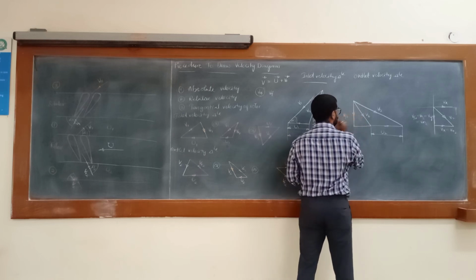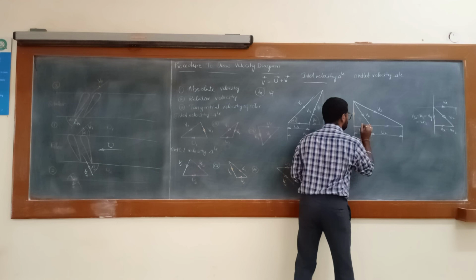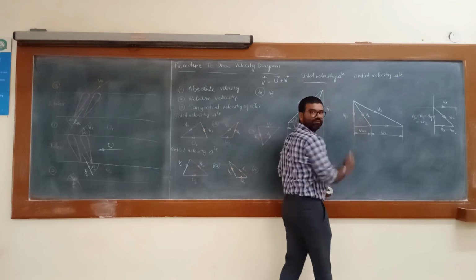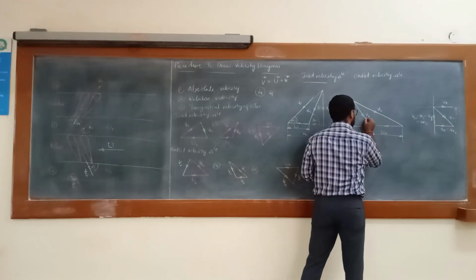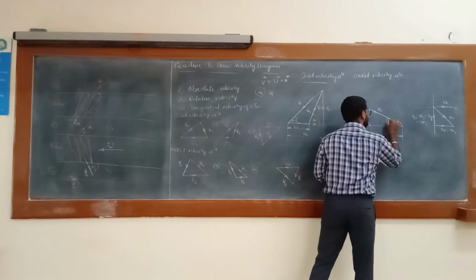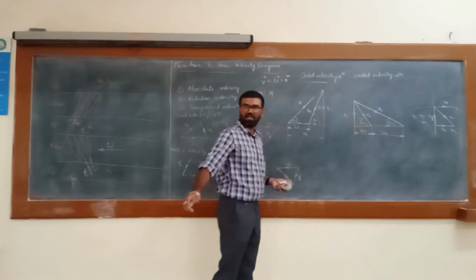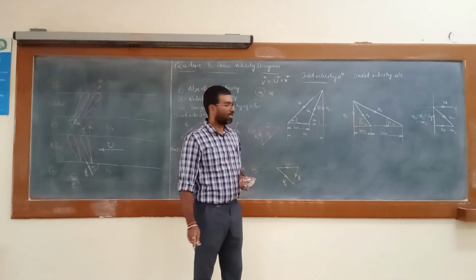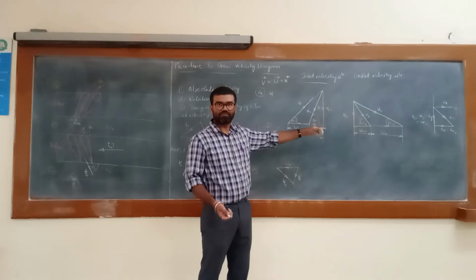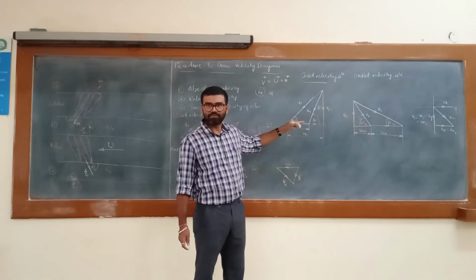This is Vf2 and this is Vu2, wave velocity component for V2, flow velocity component for V2. Understood? Okay. What are these angles? This is alpha 2 and this is beta 2. This is the outlet velocity triangle. This is the inlet velocity triangle. Understood? Any doubt here? Okay. So these are what we call generalized velocity triangles. We are going to use these velocity triangles in future also. Okay, nice.